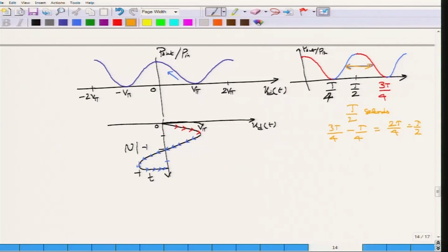So you have now obtained one pulse of duration T by 2, but if you look at this way and then realize that this signal is not just one period, but this is actually a periodic signal, you would immediately realize that there would be one extension this way and there would be an extension along this side as well. So this is your T actually, the total time period T, and in that time period T you have actually managed to obtain two pulses, right.